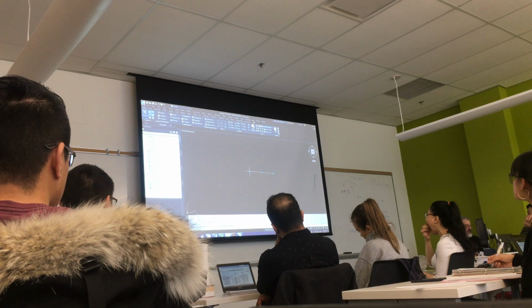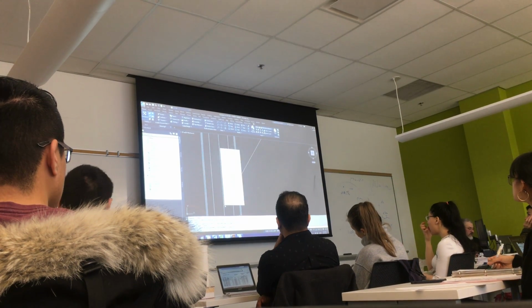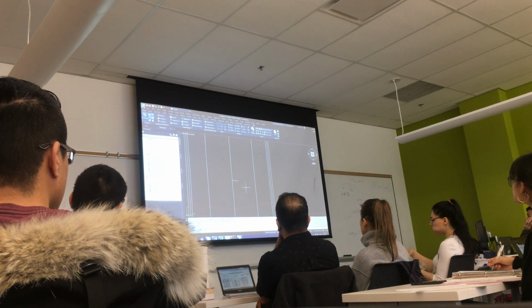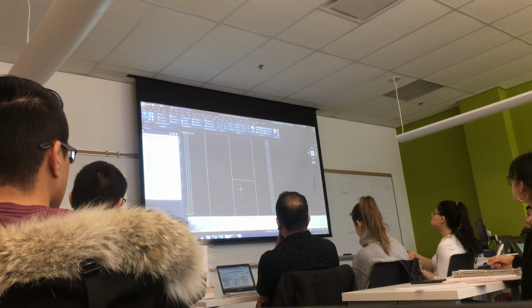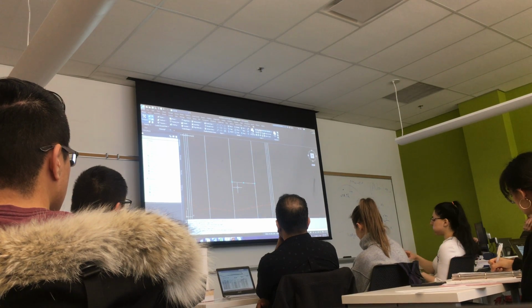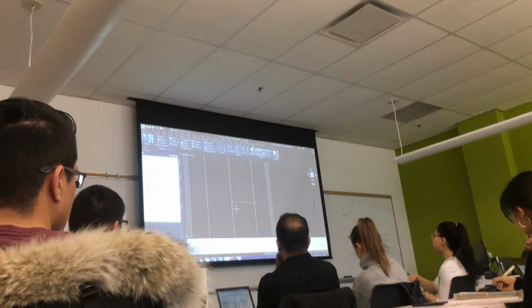Take this, move it from this end point, and put it right where the design of the crown is. Remember this point? Right? I don't need this reference anymore. Extend it the full width of the lane. Right? I don't care how long this is. The width of the lane is exactly 3.7. This line's going to be a hair longer. Ignore that. Never measure on the 3D. Always horizontal or vertical. Okay?